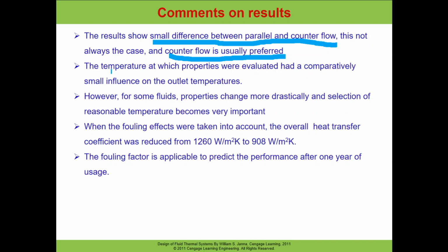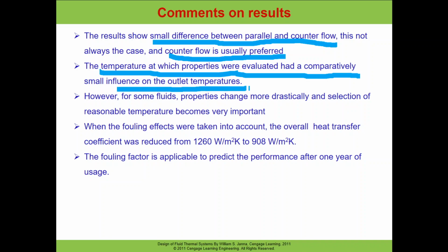What about the properties? The temperature at which the properties are evaluated had a little influence on the outlet temperatures, but this is not always so. Sometimes the change of property is big with respect to the temperature, then it has a large influence, and sometimes the change in property is small, then it has a small influence.